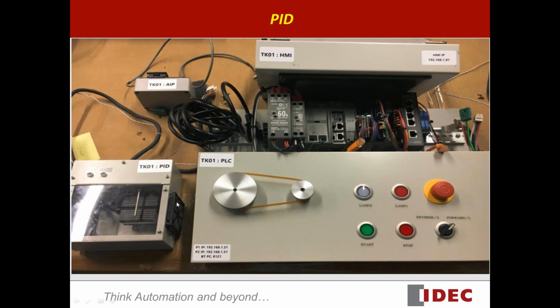Okay. Now the PID output, guys, again, I don't know if somebody noticed, everybody knows the PID output is a data register variable. I'm going to take that variable and pulse that heater, because that's an on-off heater. Pulse it to control the temperature inside that box.